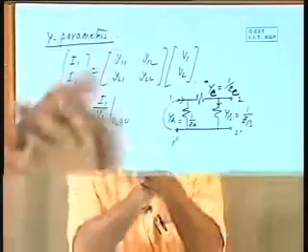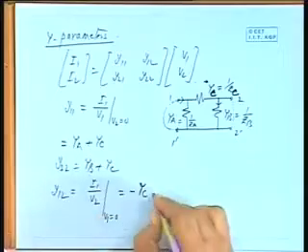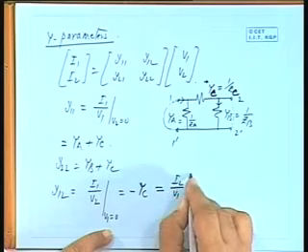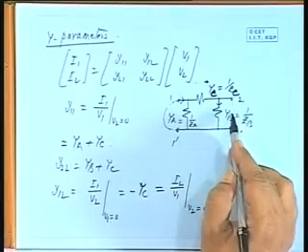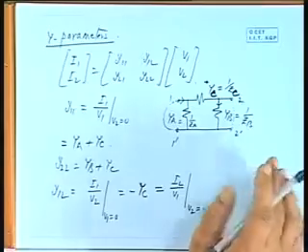Now, if you are given these Y parameters, there is a black box given to you with 2 ports, 4 terminals, and I ask you to perform this short circuit test. You short circuit one side, 2 dashed, make a measurement from this side, the current on the other side, voltage and current at this end. That is, you measure V1, I1, I2. Again, excite the other side, short circuit 1 dashed, apply a voltage V2, and measure I2 and I1. So you will get all the 4 quantities. This is also I2 by V1 by the same logic when V2 is 0, when I short circuit this, apply a voltage and measure this current. Is it all right? If you are given these parameters, but inside I don't know what it is, there can be a number of elements interconnected.